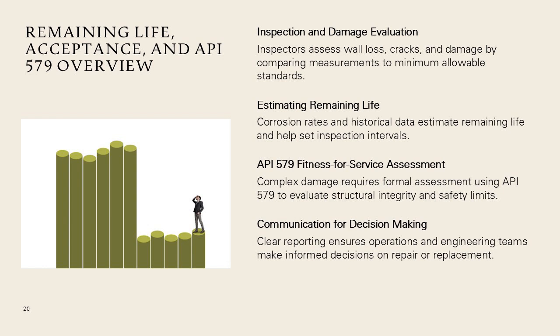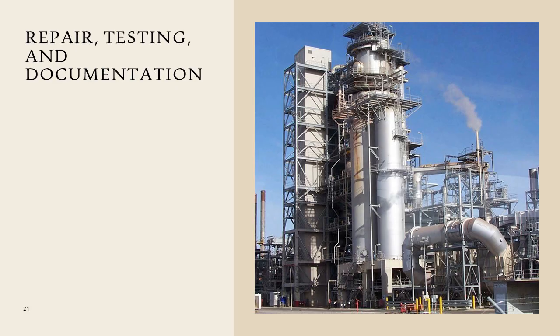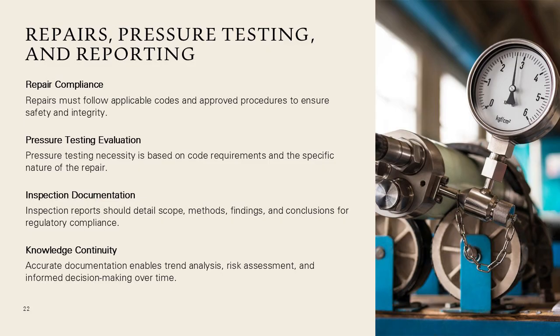Clear communication of evaluation results and recommendations is essential so that operations and engineering can make informed decisions regarding continued operation, repair, or replacement. Repairs, pressure testing, and reporting. When repairs are required, they must be performed in accordance with applicable codes and approved procedures. Inspectors are responsible for verifying that repairs meet design requirements, use qualified welding procedures, and are properly examined after completion.